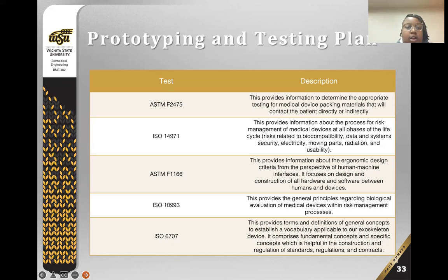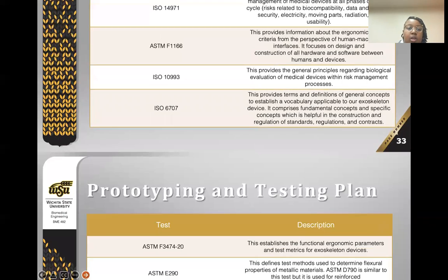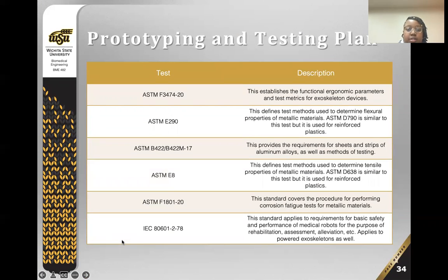The key engineering characteristics we focused on included adjustability and exoskeleton range of motion. For the prototyping processes, we plan to use ASTM and ISO standards to better develop our prototype models. Our critical design experiment and the following tests we plan to perform are listed in the table below, as well as the next one. An important component of selection testing is computer-aided databases. More specifically, we use SolidWorks to compare different materials and run stress and FEA analysis to choose our materials.